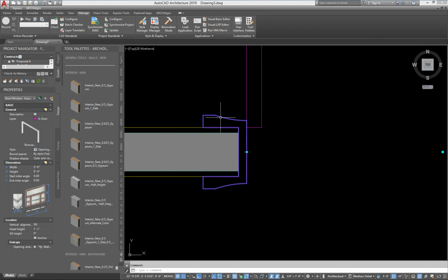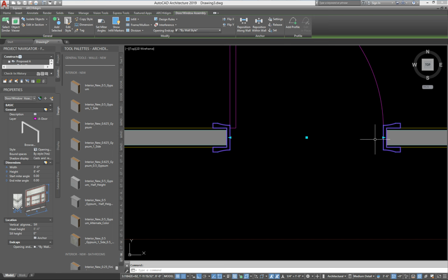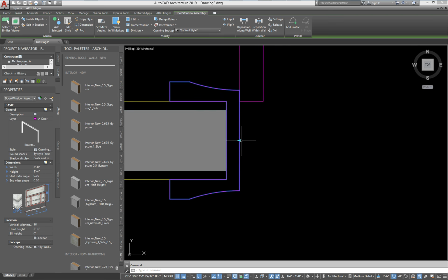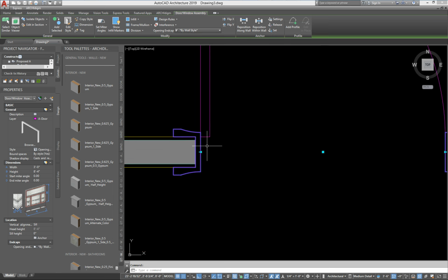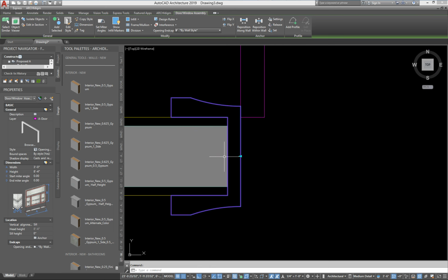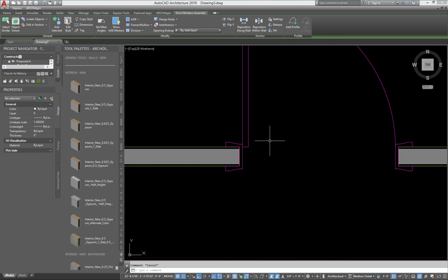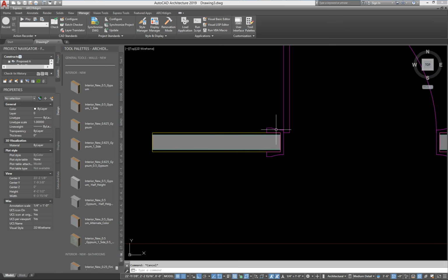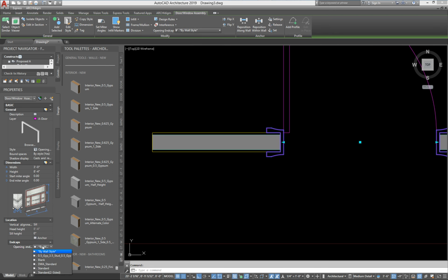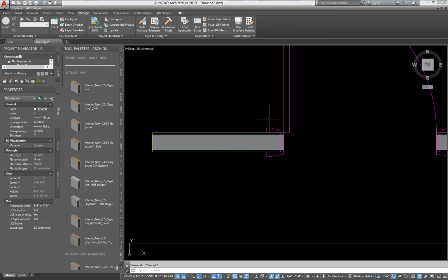And when I select this, you'll notice that even though this is a DWA, it's actually reading to the inside. If you build DWAs, you'll notice it always defaults to the outside. So we did a little offsetting to make this happen. It's 3/4 of an inch on all of our styles. And if I did not have a custom end cap style to create this solution, this is what would happen. If I go here and go to standard, this is what would happen.